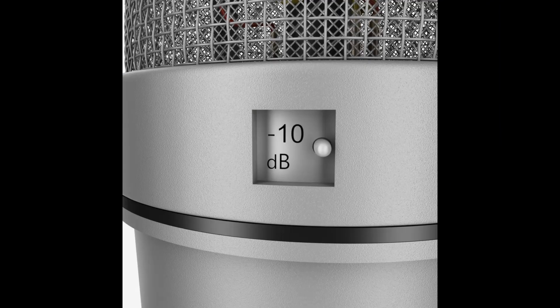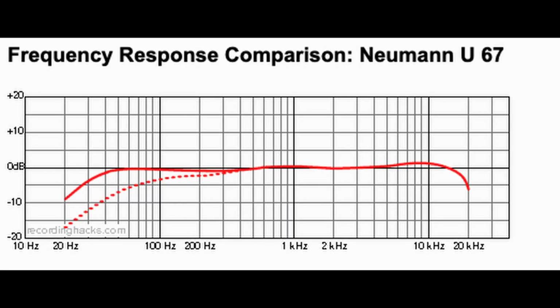These microphones almost always have a built-in pad to take care of the preamplifier circuitry inside the microphone. Additionally, this heightened sensitivity is going to bring a lot more high end that could often be perceived as harsh, whereas a ribbon microphone is more known for a warmer sound that rounds off any of those harsh frequencies. The use of all three types of these microphones is going to be very situationally dependent.